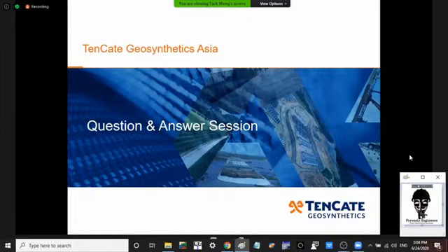First question, Tarling. What type of piles are typically used for pile embankments, and what is the typical pile spacing? Thank you for the question. There are many types of piles that are used for pile embankments. Typically, concrete piles are commonly used, and they can be in the form of driven piles, even jacked-in piles, and sometimes cast in situ piles.